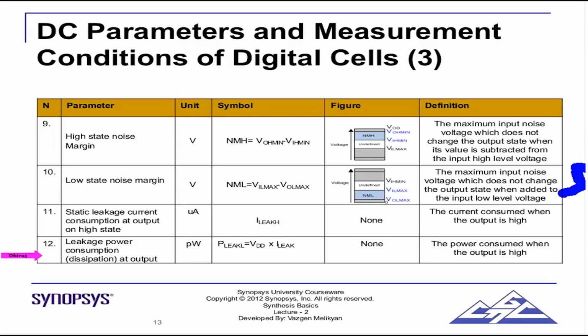What we do, for example, is choose to do synthesis only with high VT cells. So we ignore standard VT and low VT to make sure our design, to start with, has the least power, the least leakage power. It can be used in synthesis, but it is not necessary. If your library has multi-VT cells, then you could choose to use them in synthesis.